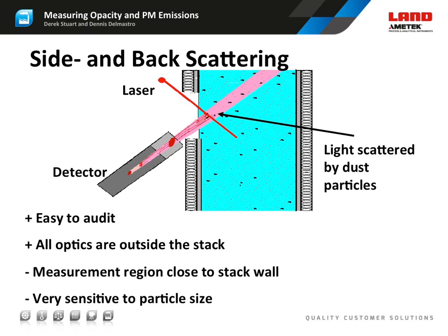They share similar pros and cons. There are no optical components inside the process, so nothing is exposed directly to the hot, corrosive combustion gases. Because the unit does not penetrate into the stack, it's possible to perform a calibration audit without removing the sensor from the process. This makes life easier for the user.